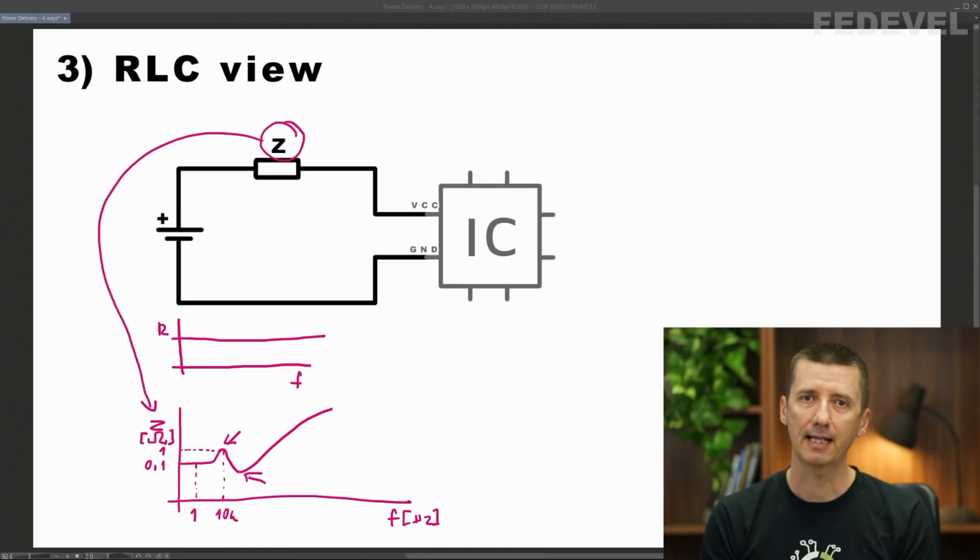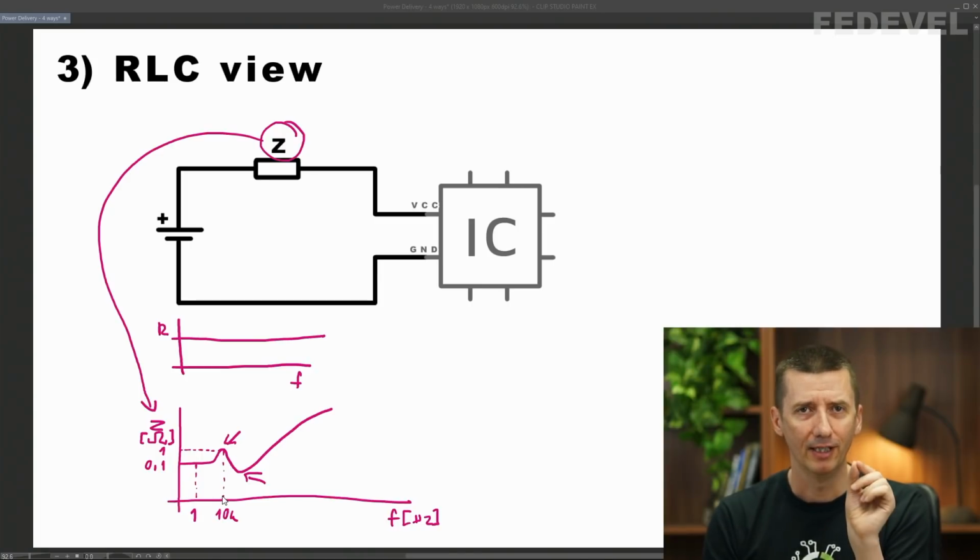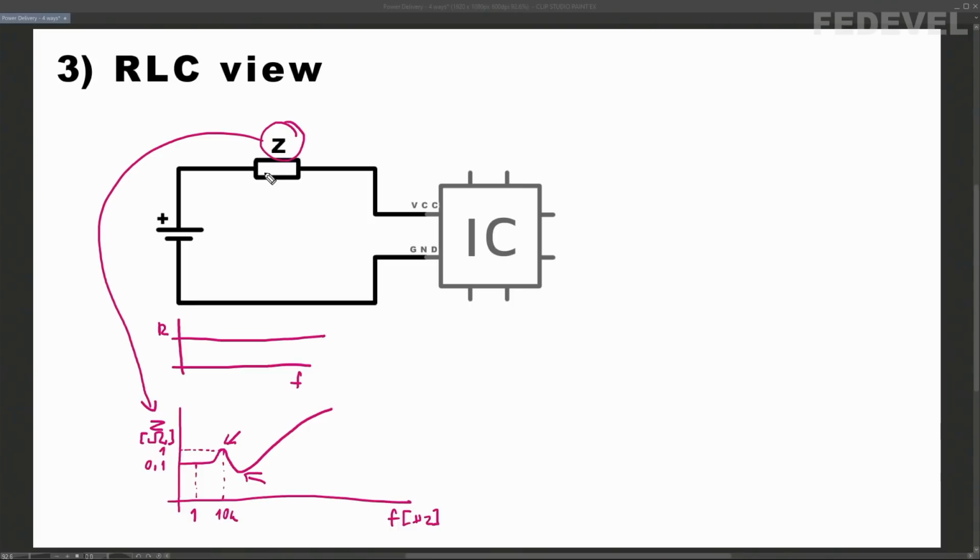And sometimes it may look like these peaks and dips are very small, but think about it. Do you remember what was the maximum resistance we calculated for our circuit? It was like 0.165 ohm. And the impedance peaks in this PDN graph can easily be 1 or 2 or 10 ohms, but only for specific frequencies. And if the impedance increases from 0.165 ohm, that is our maximum resistance we have and which we calculated, if this impedance increases to 1 ohm,